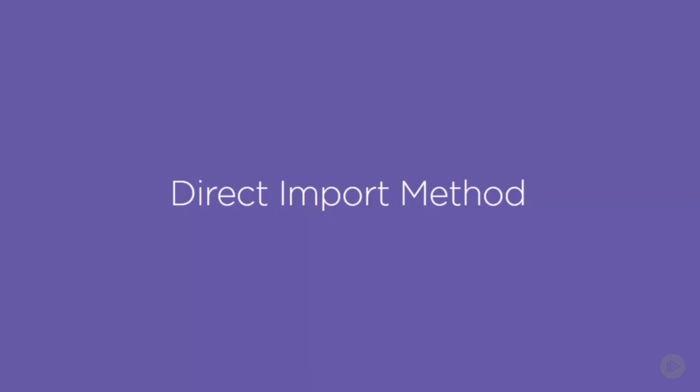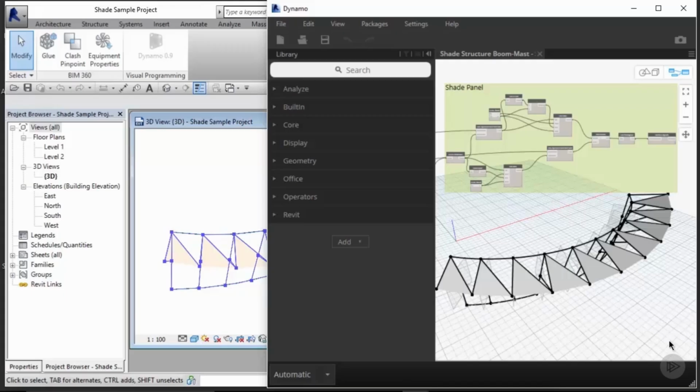Our goal in using the direct import method is to format the Dynamo definition to use components that will automatically update in the live Revit modeling environment. This is what I refer to as the direct import method. Since the shading structure is relatively simple in how it's built, we will use a basic adaptive component in order to stretch a triangle across the shading structure panels.